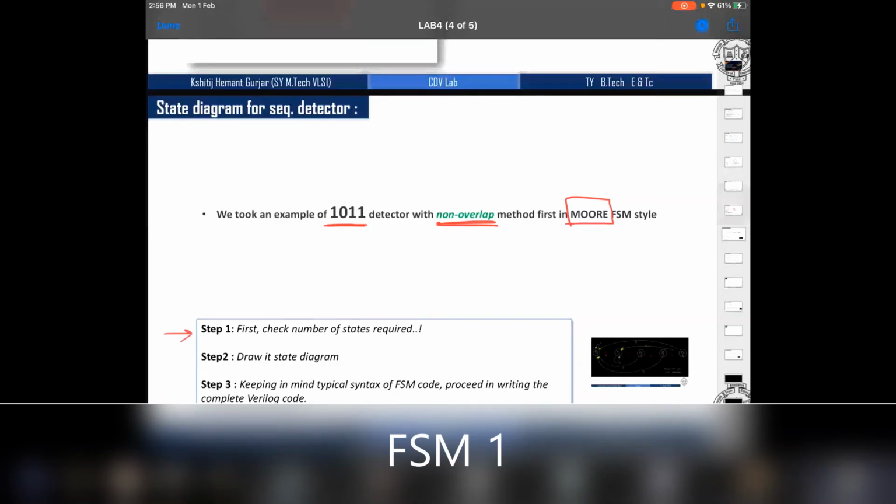You can remember this like it's Moore, right? Moore actually requires more states than Mealy. One extra state is there in Moore. You can just omit one O from it and remember it as more, so it requires one more state. As it is 1011, 4 bits, we require one extra state, that's why 5 states, right? Okay, so there are steps to follow. Anyone having doubt?